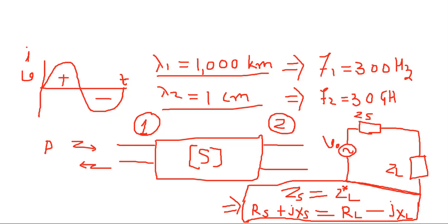So all the devices will be different. Although diodes work at low frequency, diodes working at high frequency are designed differently. Transistors at high or microwave frequency are designed differently. Passive devices are called the microwave bench. If you want to transmit a microwave signal, it cannot be transmitted through a twisted wire cable, because the losses will be very high. The impedance matching comes into the picture. So either you can use a waveguide or a coaxial cable, and again impedance matching is required there.